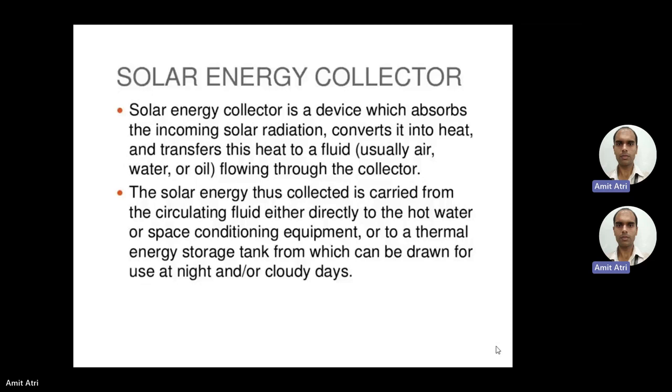Solar collectors are classified as low, medium or high temperature collectors. The name indicates low temperature, medium temperature and high temperature. Low temperature collectors are used for smaller non-intensive requirements common in the household, usually at less than 150 degrees Celsius. Medium temperature collectors are used for heating water or air for industrial and commercial use, in the range of 150 to 400 degrees Celsius.